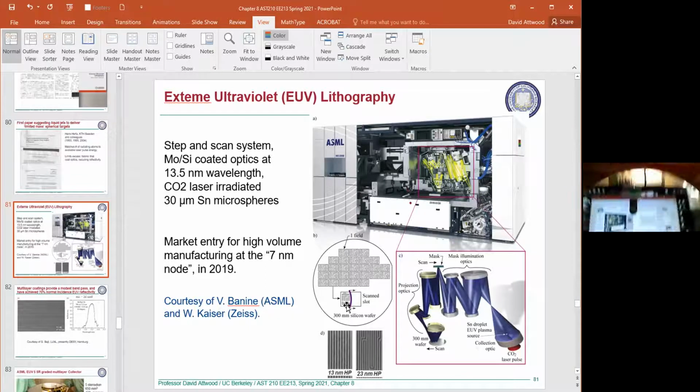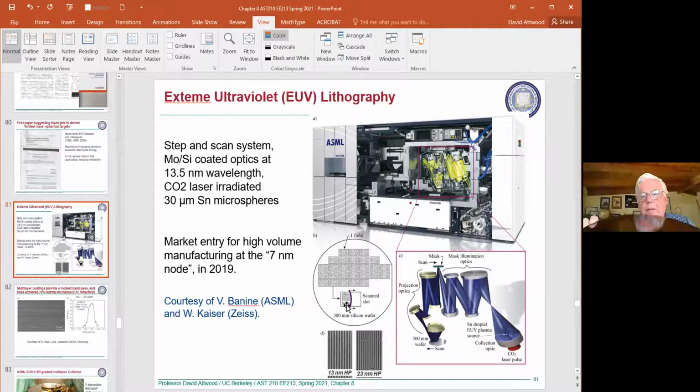This is a silicon wafer. This is what they print computer chips on, okay? And it's super flat, and they put a coating on it, a so-called resist, a system of molecules that when light shines on it, it breaks bonds, and you can fix it then, and you'll have a feature.